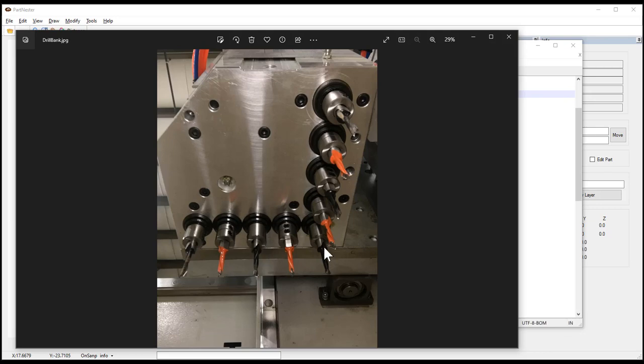So if the machine is only going to use drill number 1 and drill number 2, binary 1, binary 2, we will add those two together and you will get a value of 3, which will then put down 1 and 2. If we only want to have the drill number in the far left here in the X direction, again we are binary 1, 2, 4, 8, and 16, the call to put down drill number 5 would be just a 16.